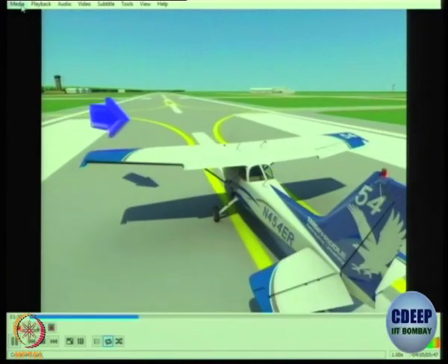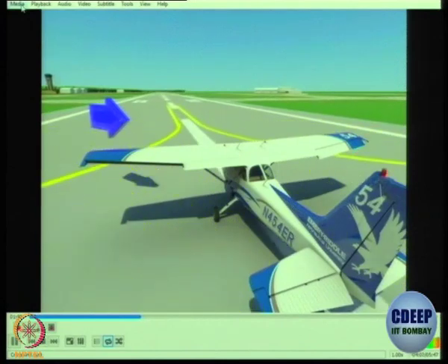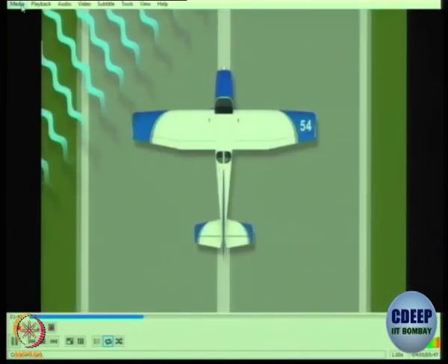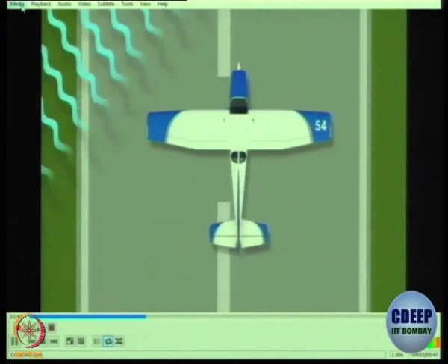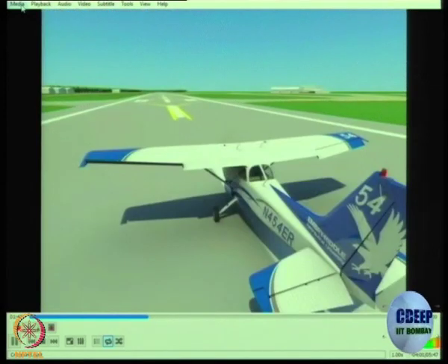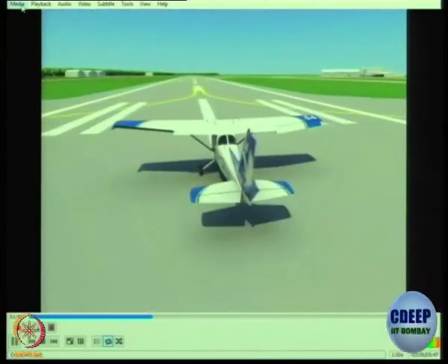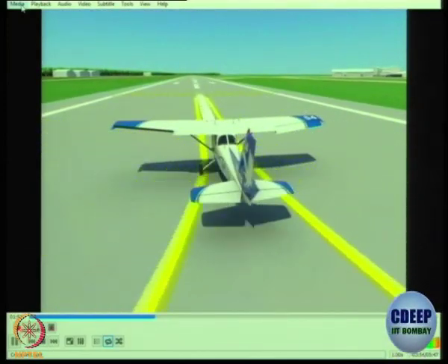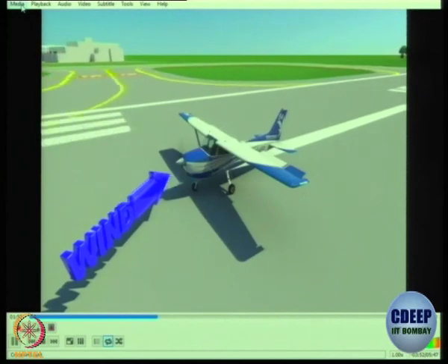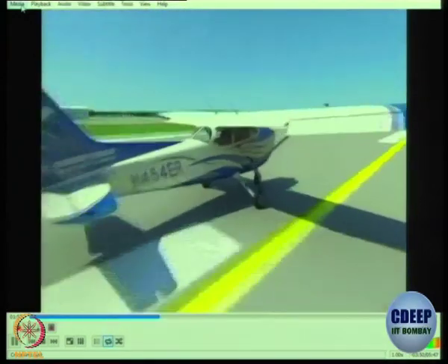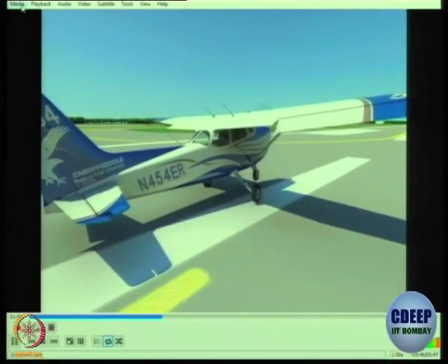Consequently, aileron input will be used throughout the entire takeoff. With improper crosswind correction, the airplane may begin to get pushed off centerline. This side loading causes stress on the landing gear, so it's important to use aileron correction throughout the entire takeoff roll. As the airplane lifts off the ground, the downwind wing and wheel should rise and lift off the runway